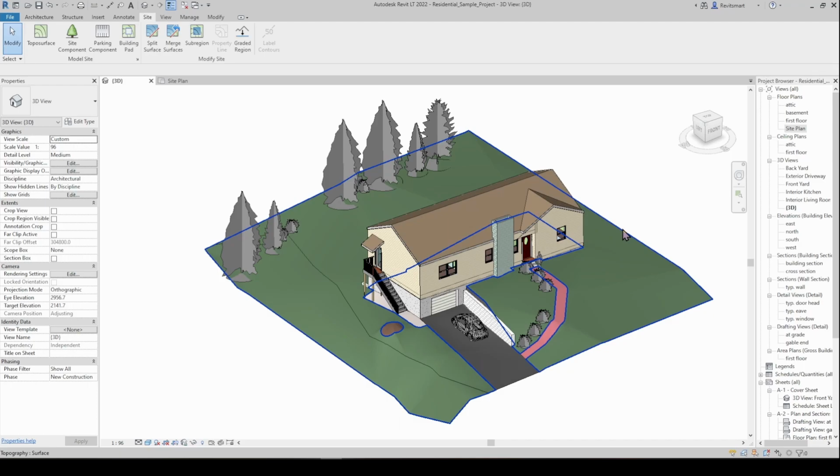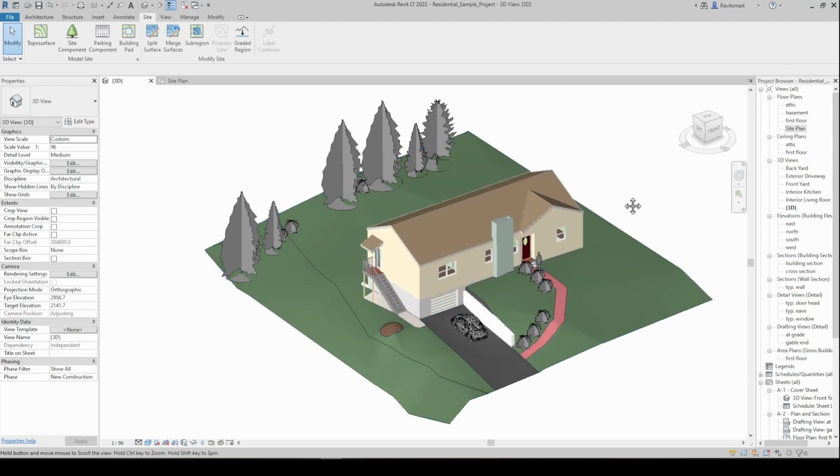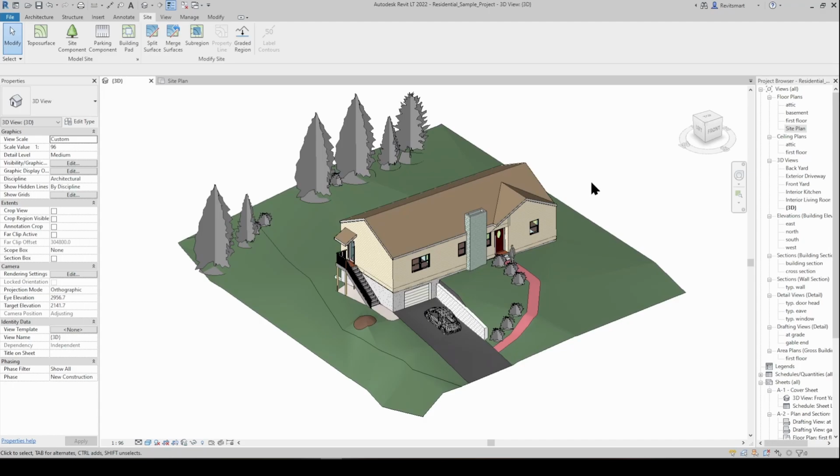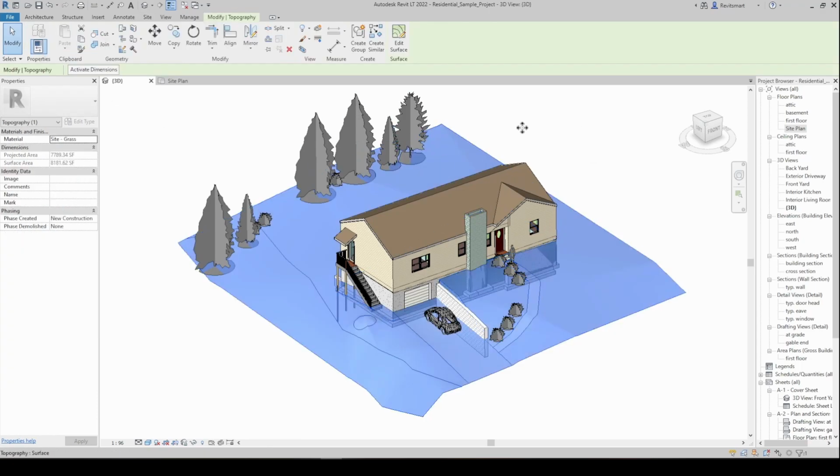When I say suit your needs, I mean you can work out the extents of cut and fill, and you can work out exactly how long, for example, a batter bank needs to be, which is like a grade in the land. It's something that has to be worked out quite accurately, which is why a couple of the tools that Revit actually provides are pretty trash. So Topo surface itself, like I said, it's just the land.